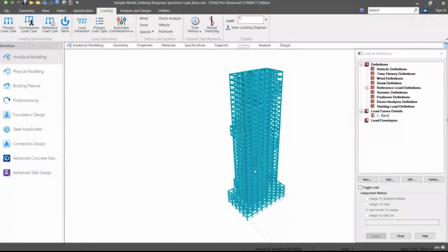Next is the mass participation factor. The mass participation for each mode along with cumulative mass participation till that mode for X, Y and Z axis are reported in this table. This table is very important and we need to review the mass participation factors. I will discuss this in detail. Base shear value is reported for 4 modal combination methods, though we have specified only the CQC method as modal combination method.